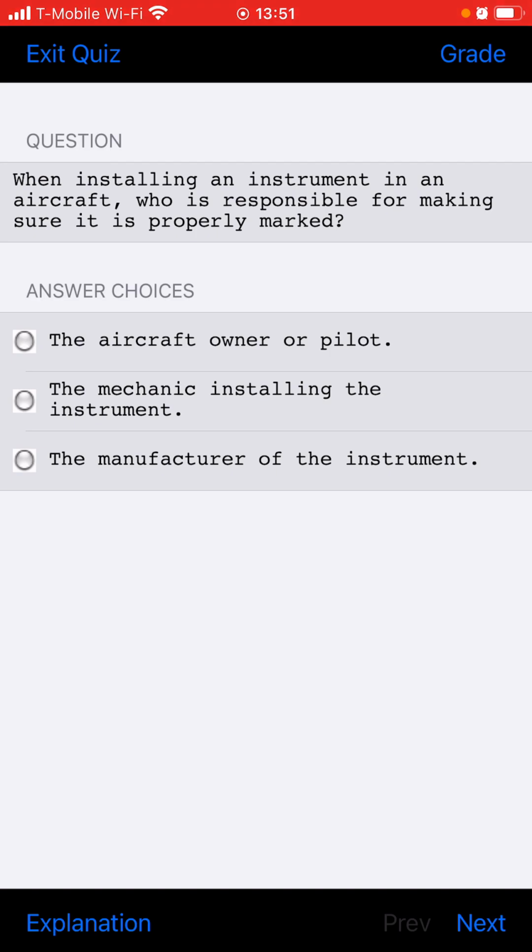Under what condition may any checklist be used as a guide for a 100-hour inspection? The checklist must meet the minimum standards specified in the FAR Part 43, Appendix D.